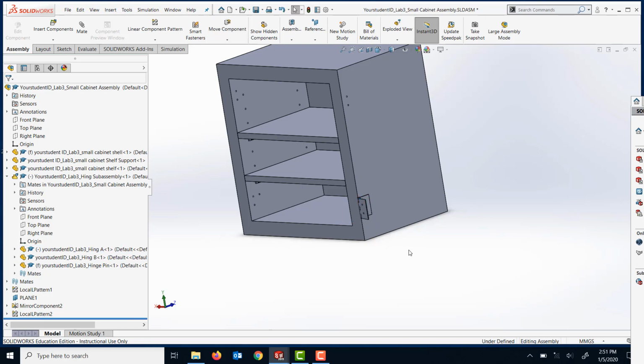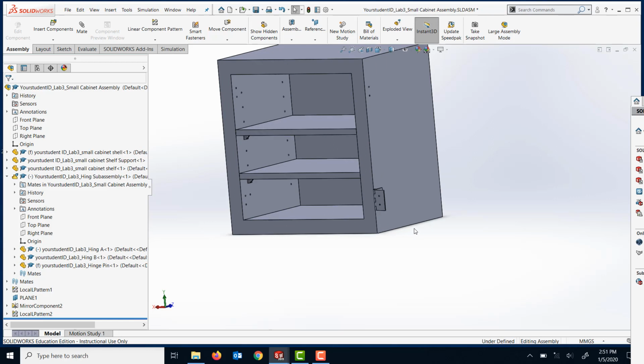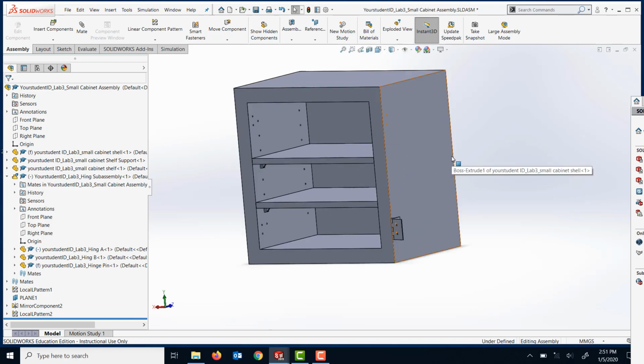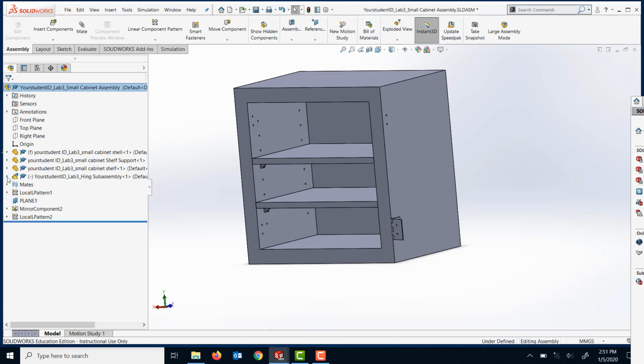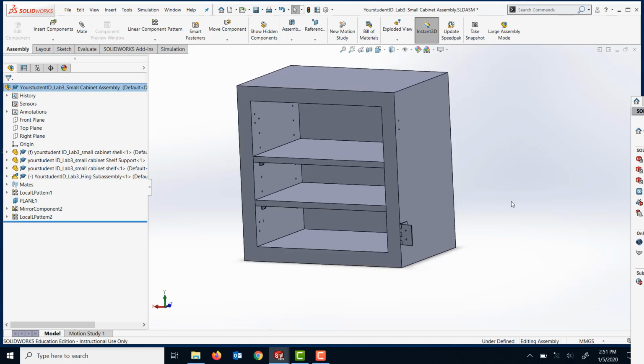So basically you need to make your subassemblies flexible. Always it depends on your design intent what you want to do. Sometimes you want it to be rigid because whenever you open your assemblies, you don't want to waste too much time, because it adds to the computational power.